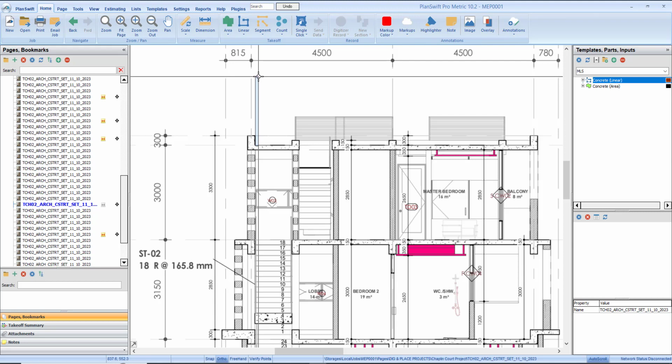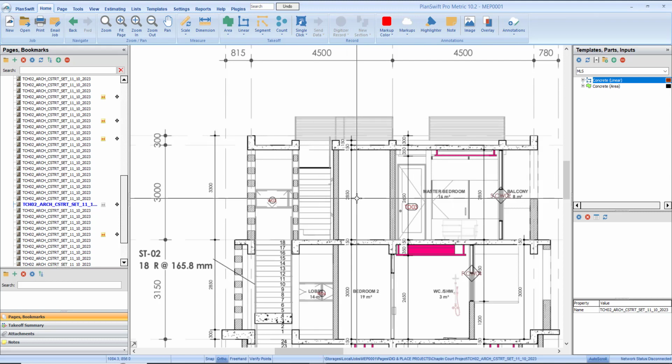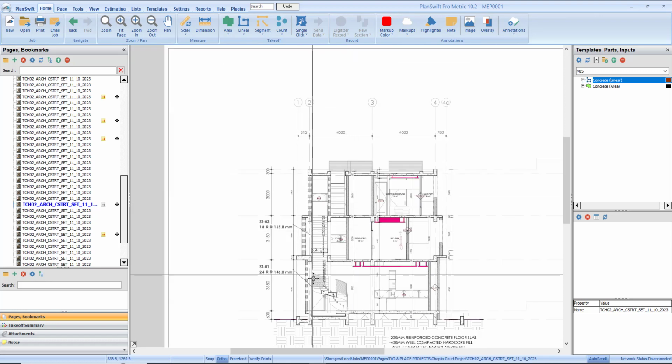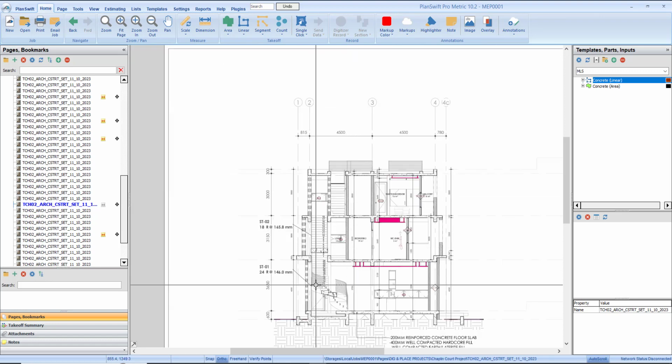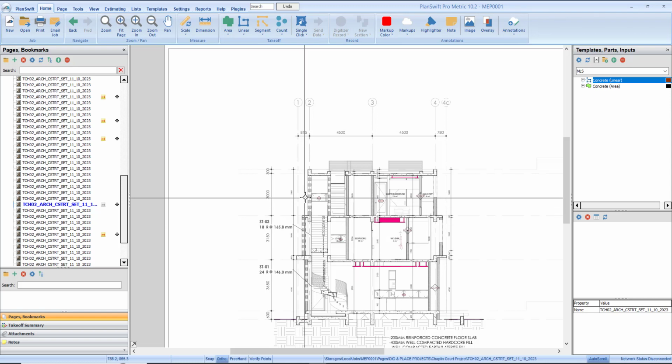And then be able to include the offset of this vertical pipe that is in the duct. And then you will know the height or the length of the total pipe that you need for the riser pipe, which is our 32mm supply pipe.